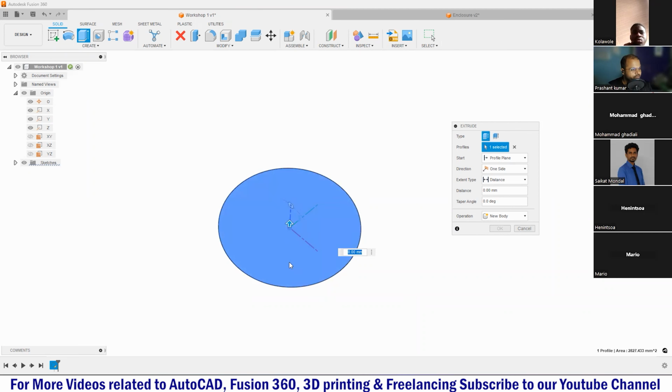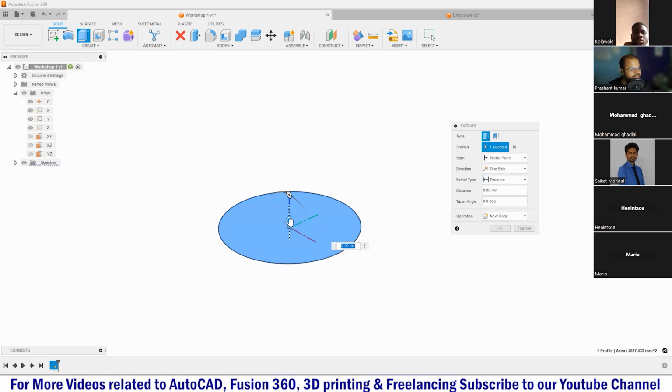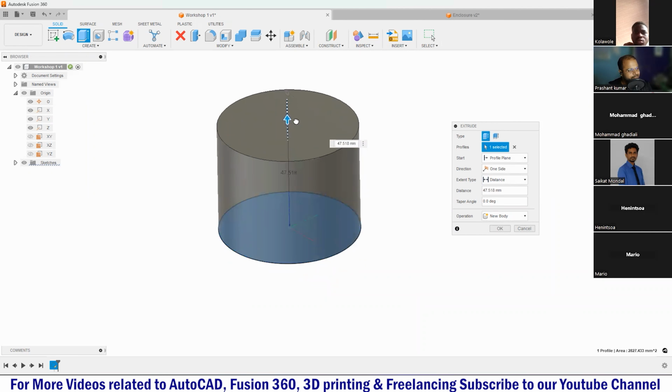All the time, if you want to orbit it a little bit to reorient your view, you can do that just by pressing shift and the middle mouse button. And you can just click on the arrow and drag it to give it a 3D shape. Here you can see it's really easy. Now just drag it like this and put your dimensions. Like let's say I want to extrude it by an amount of 30.